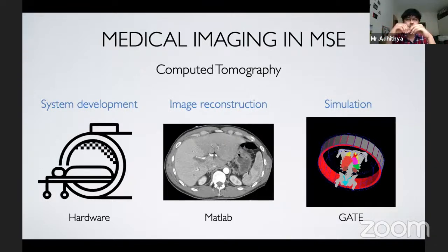There are various scintillation materials in use. I think cesium iodide is one of the commonly used, and there are different variations of scintillation materials. These materials convert your X-rays into visible light. And visible light is converted into signals using photodiodes and other electronics.